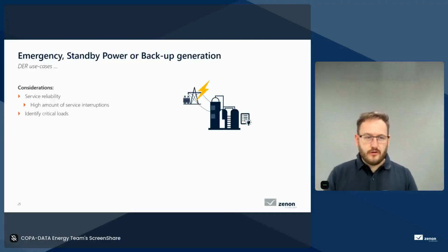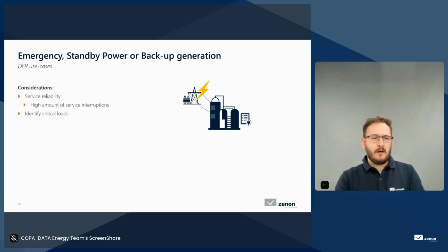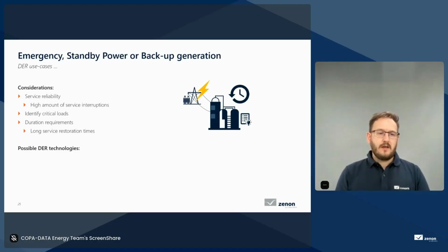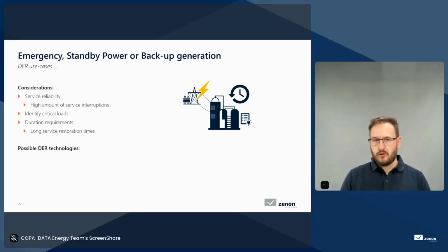Then, always a good consideration is that we need to identify our critical loads. It could be critical infrastructure, like a hospital. Certain devices obviously need to have standby power in the event of an error. Then we also need to identify the generation requirements for our emergency or standby power. How long is my service going to be unavailable? Maybe the DSO utility has long service restoration times, things like this. So these are considerations we need to look into.